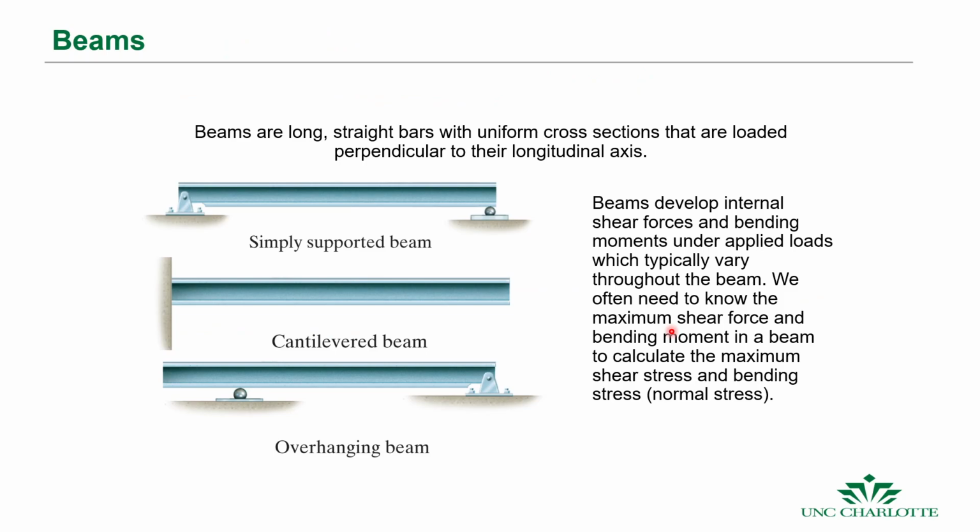So the first thing we're going to do is talk about the flexural formula, which is the bending stresses that are developed in beams. Of course, we have beams that have different types of loads: simply supported, cantilevered, overhung. When these are loaded, they develop internal shear forces, and we know that the bending moment is the integral of the shear at that point. So we often need to know where the maximum shear forces and bending moments are in a beam,